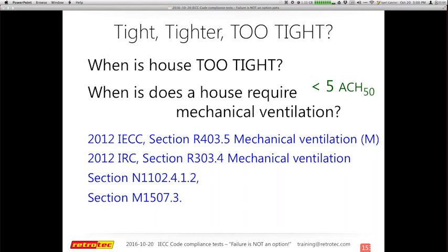A couple more there, Joe. There's one for a blower door test in 2015 code. Is the dryer vent left open or tape closed? Great question. You're not allowed to cover anything that's artificial. So if you are doing a blower door test and the dryer is not there, maybe it's actually the exhaust fan is not there, that these all have dampers besides the ones that are built into the device that you're checking to make sure that they're working.